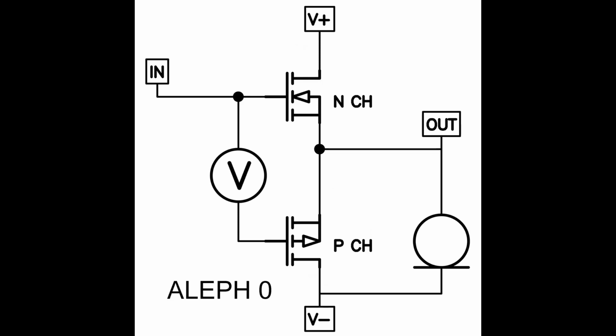About 20 years after that, I designed the LF0 power amplifier, which used a complementary output stage paralleled with a large constant current source. The push-pull output stage was already Class A with a heavy bias current, and it already had very low distortion, but I wanted a single-ended characteristic.